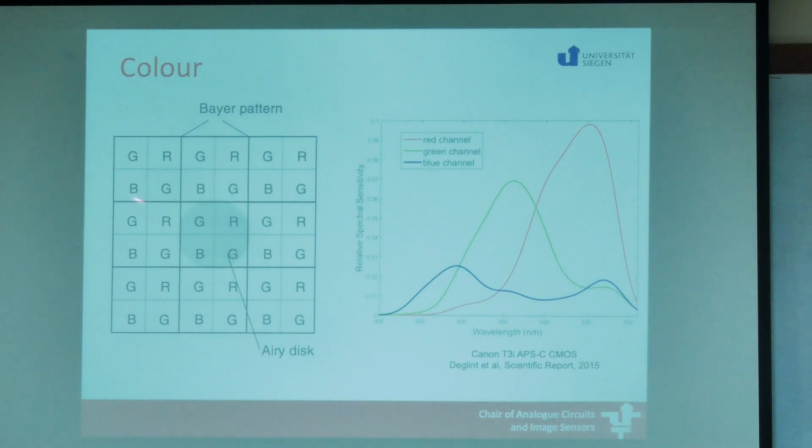Now, if we do something like this and say I have got a 10 megapixel imager, what you would see is that half of that, 5 megapixel, is green, a quarter, 2.5 megapixel, is red, and 2.5 megapixel is blue. Now comes the next stage. How do we get color out of it? What you could do is consider all of this as 1 pixel. So we take the average of green, we take the red, and we take the blue. We have got red, blue, and green. We can take color out of it.